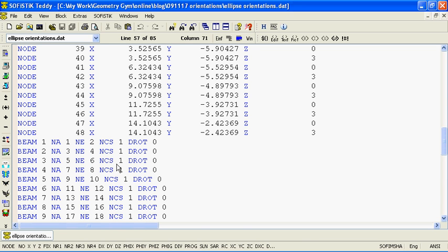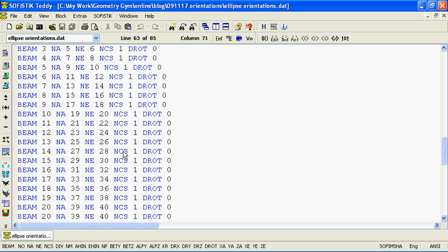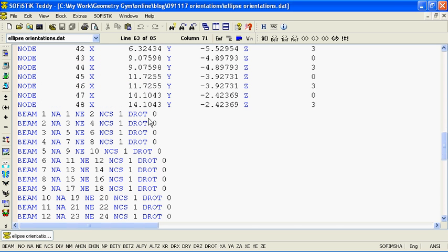Okay, what we're going to look at today is how you can use the structural drawing tool plugins to control the orientation of your structural elements in your model. Typically by default, most elements have their local axes with the z-axis oriented in the vertical direction, but for vertical or column elements, this is generally a predetermined direction for the analysis program.